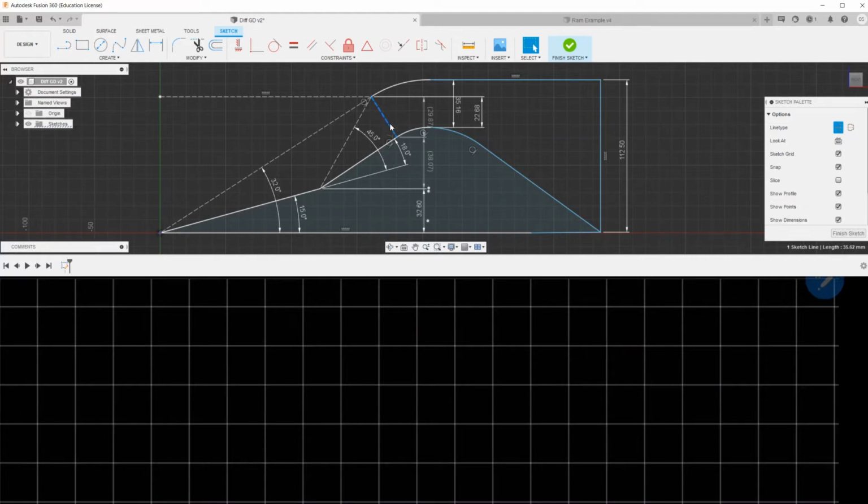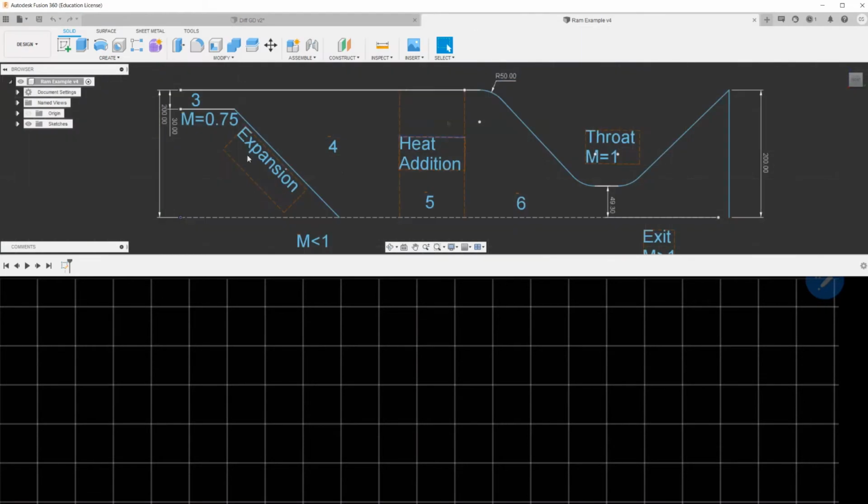We first calculate a diffuser. We calculate what the flow properties are inside the diffuser. And with these flow properties, we calculate, using the Mach-area relation, the flow deceleration here, and the pressure here is the consequence of the diffuser calculation.